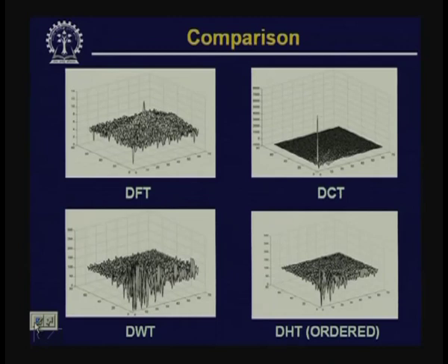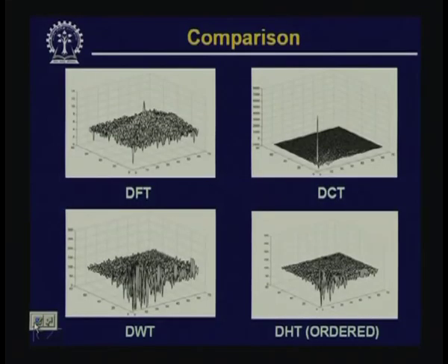That is why the discrete cosine transformation is very popular for data compression operations, unlike the other cases. In case of discrete Fourier transformation and discrete cosine transformation, we can associate the frequency term with the transformation coefficients, but it is not possible to have such a physical interpretation of the coefficients of the discrete Walsh transformation, nor in case of discrete Hadamard transformation.